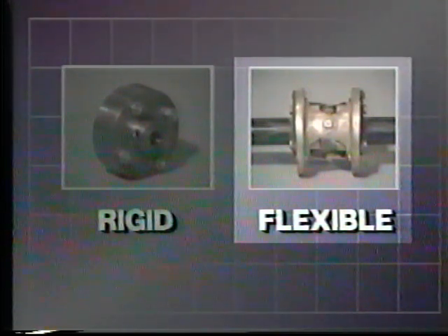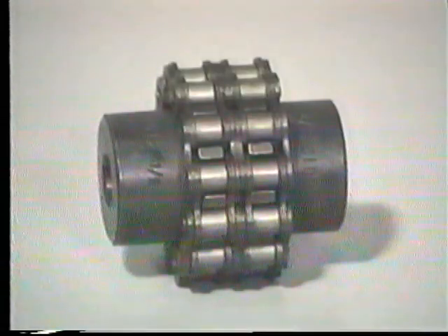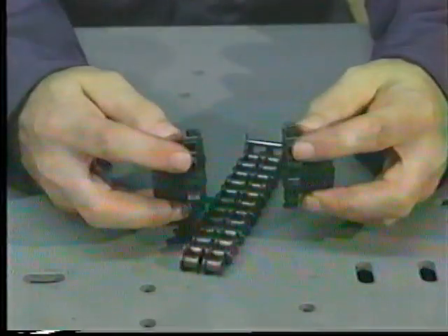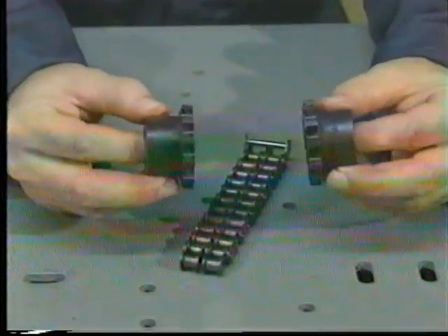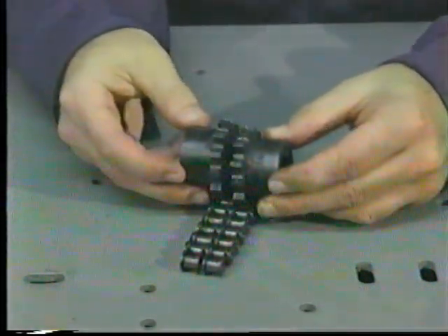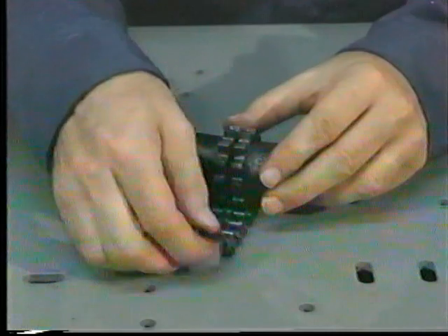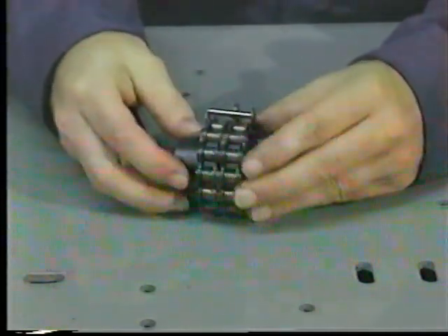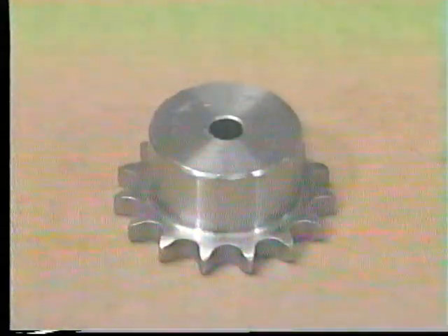movement, or deflection. Many different types of flexible couplings are used, but probably the most common is the chain coupling. Chain sprockets with specially shortened and hardened teeth are attached to each shaft. Then, a piece of double chain is wrapped around them to make the coupling. Chain couplings are flexible enough to tolerate about half of 1 degree of angular misalignment. They're relatively rugged, and they're economical.